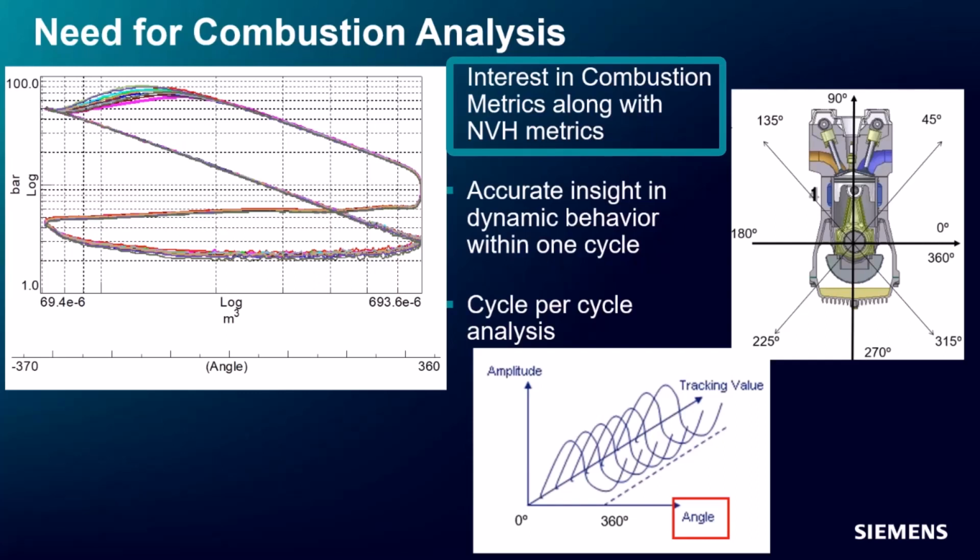Yeah, so if we change our pilot ignition or fuel injection timing, we can understand how that affects noise, vibration, as well as combustion efficiency like IMEP, etc. Yes, that's a good point, Pete. If you have one system that does both in terms of NVH metrics calculation as well as combustion metrics calculation, I think that will be really helpful in terms of making design decisions, checking the effectiveness of certain combustion countermeasures, as well as understanding what the trade-off of doing that is.